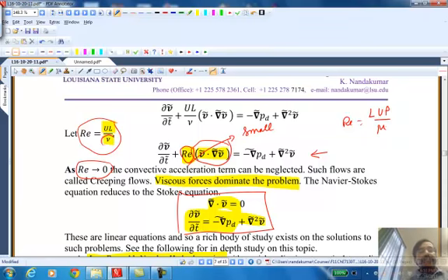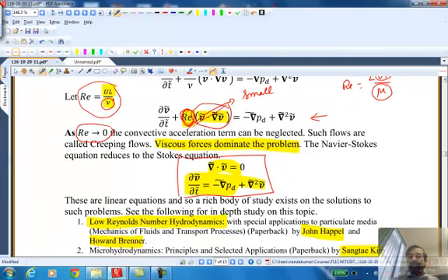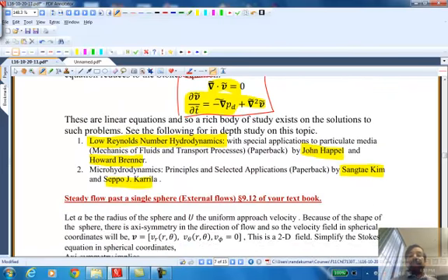Here we have written it as nu, but nu is mu over rho. So here is your mass times velocity term. That is your inertia, and viscosity is in the denominator. So when inertia is small, the Reynolds number will be small. That means I can neglect this term. We have done that for a general three-dimensional case, but we're going to go back to the 2D case to be able to solve even the Stokes equation.